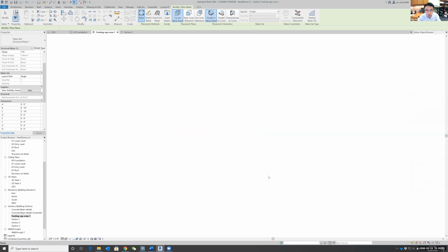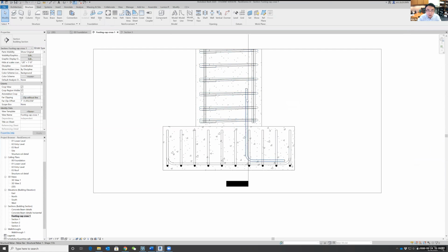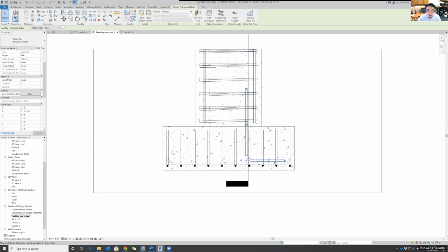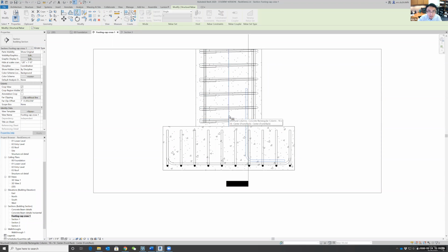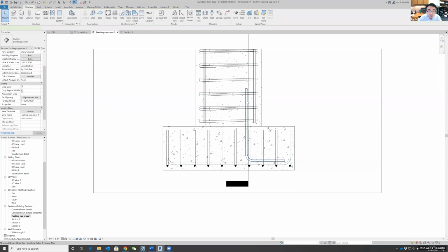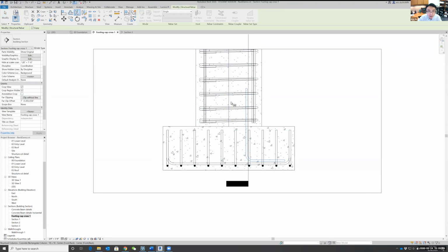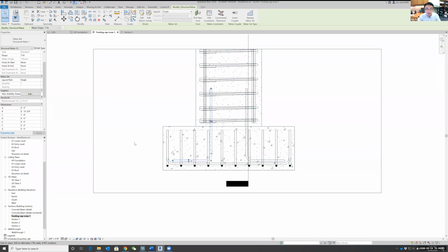And then I want to create a rebar that is mirroring this one. So instead of manually drawing another rebar, the anchoring bolt, I can use a function called mirroring. So I'm just going to select this one, and you see this one called mirror. And you basically select the central line you want to mirror it. And then, boom, you have the other one. So let me do that again. Backspace. So I have this one, I select it, and once I select this anchoring bolt, I select this mirror, and then I pick the central line here, and it basically will send the bar over there.